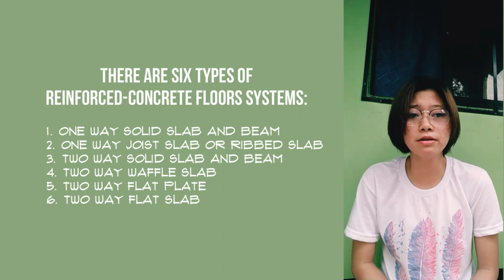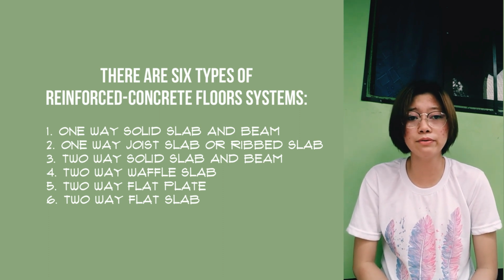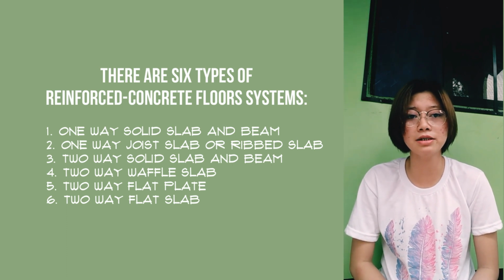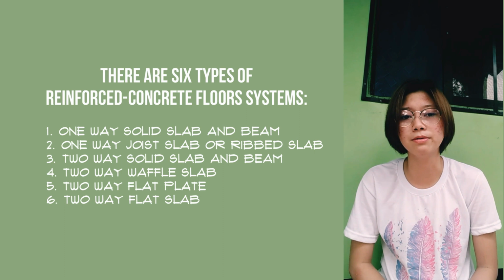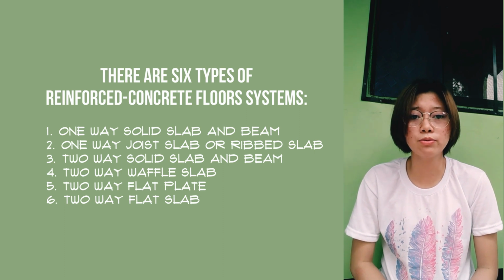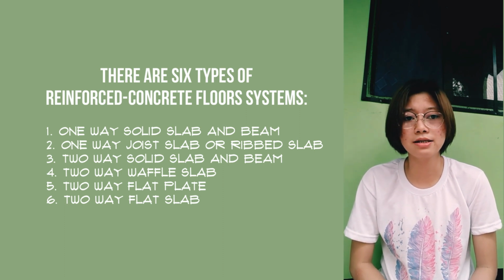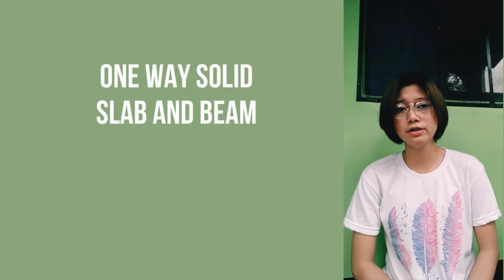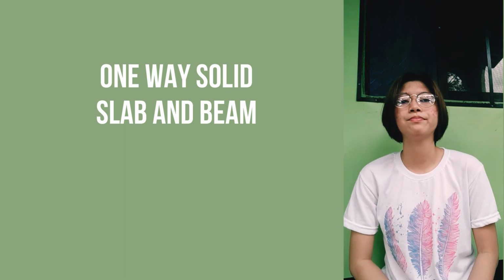Although the arrangement of the plans of a building frequently determines the column spacing, approximately square, a desirable column spacing of 20 feet more or less has proved to be most economical, but this of course depends on the type of floor construction to be used. So next, first we have one-way slabs.